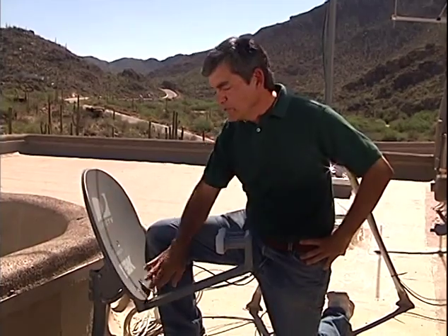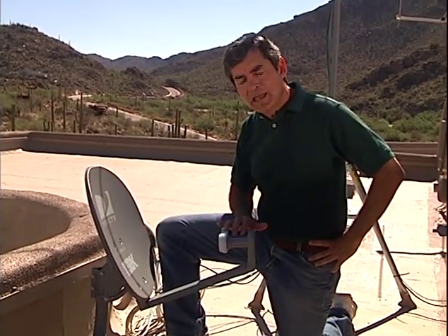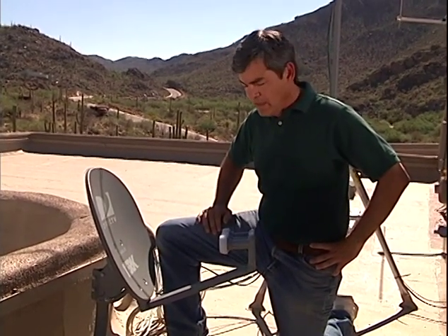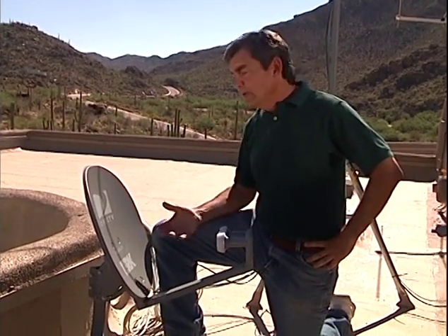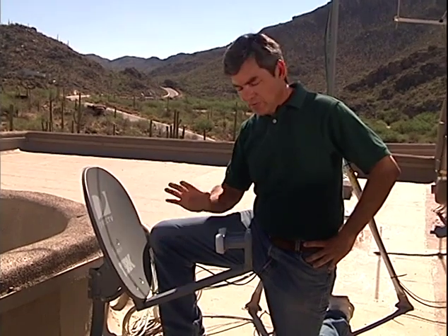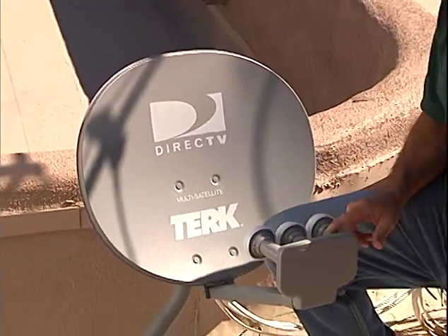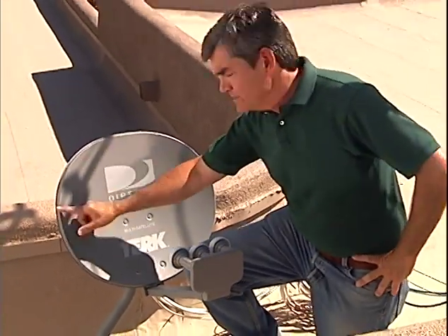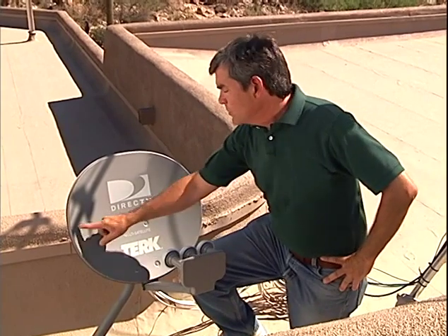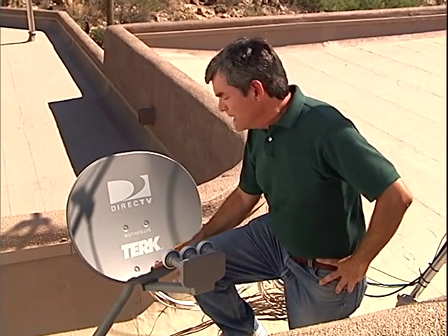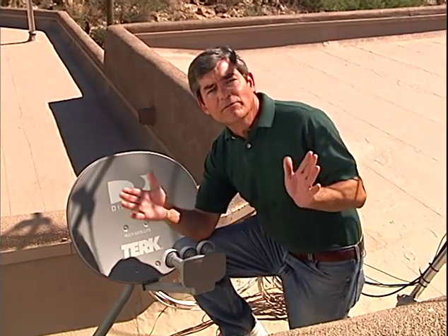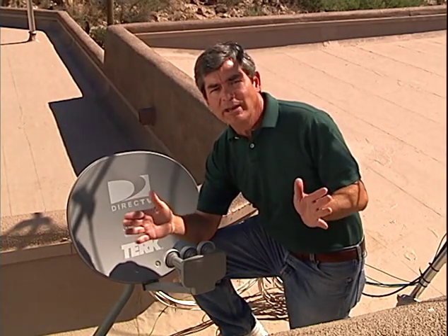The geometry of the dish reflector and the position of the LNB means that each LNB can only see one orbital position. To receive broadcasts from additional satellites at other orbital positions, extra LNBs are required. That's why the newer DirecTV dishes have 3 LNBs, one for each orbital position. Along with the extra LNBs, the reflector itself is now elliptical in shape, 24 inches by 18 inches. This is to handle the signals arriving from the 18-degree satellite spread.